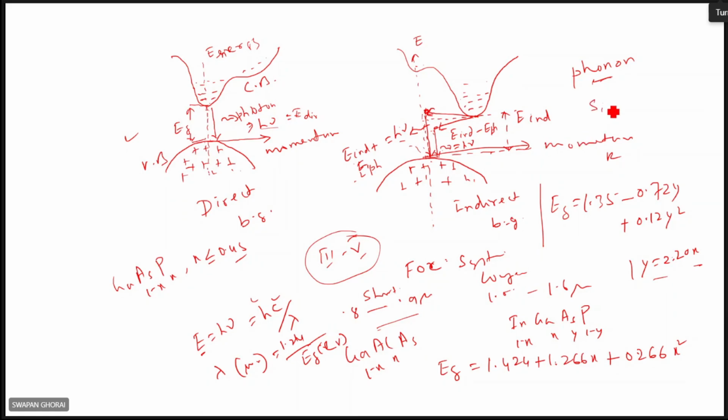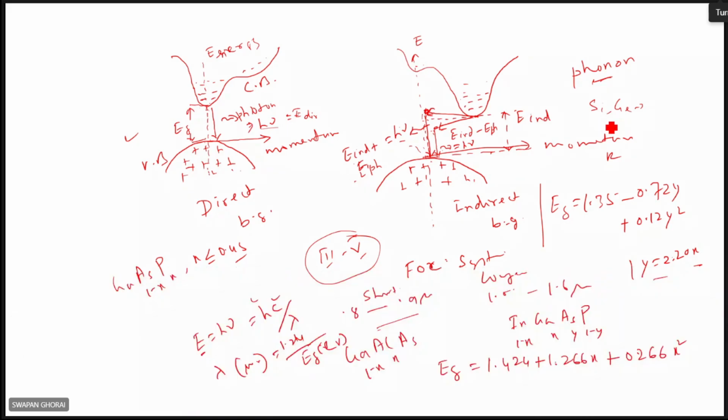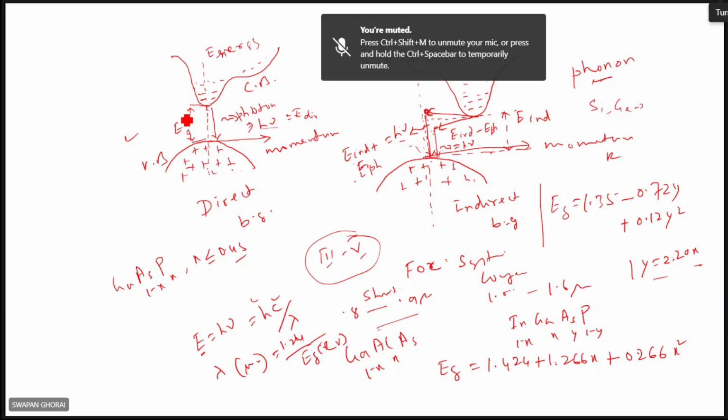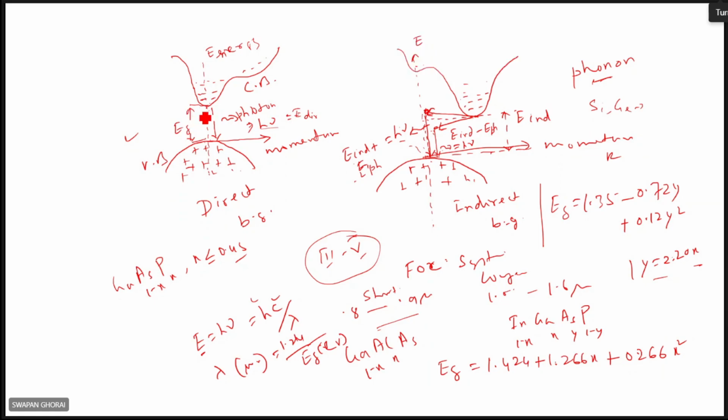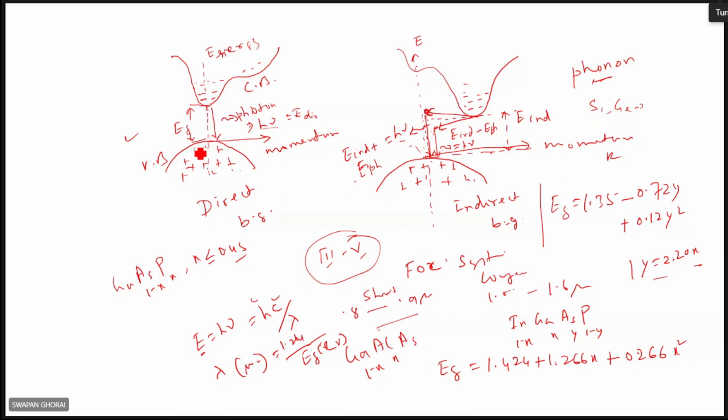Unfortunately, silicon, germanium, all these developed technologies, the single element semiconductors, they are indirect band gap types, right? So these are generally not used for LED sources. For LED sources or laser diode sources, you need direct band gap type materials, for which the conduction band minimum and valence band maximum will be at the same momentum value, right?